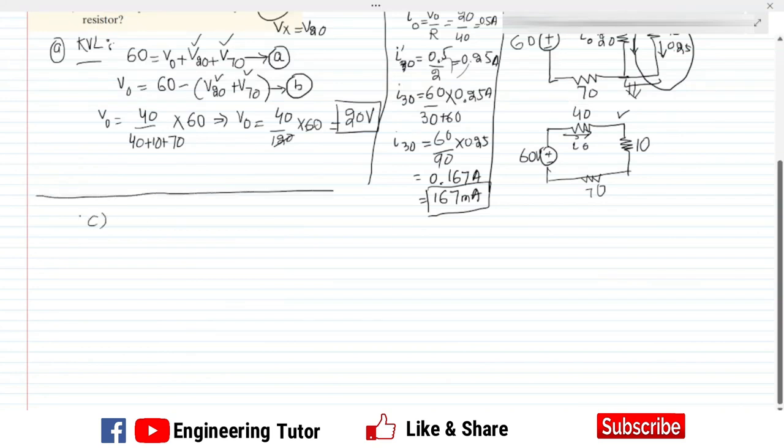So this is part C. In order to find the current I50, we note that the total current is 0.25. The current which is flowing through the 30 ohm resistor is 0.167 or 0.16. So I50 is equal to 0.09 amps.